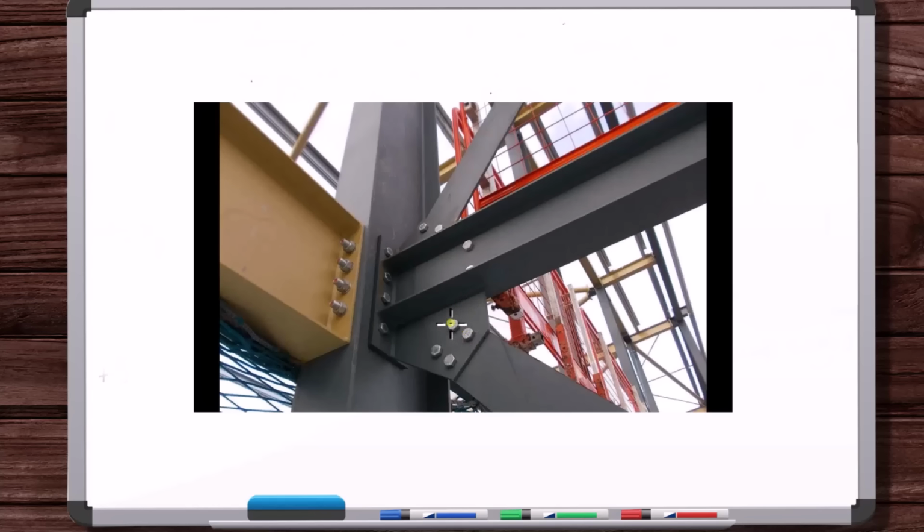But you can imagine these bolted connections don't support any rotation. They aren't preventing this beam and this beam from rotating relative to one another. You might say, well, there's friction there. But when you're talking about the enormous weight of the skyscraper or whatever this is and all the furniture on it, the friction force is negligible compared to the translational forces in the connection.